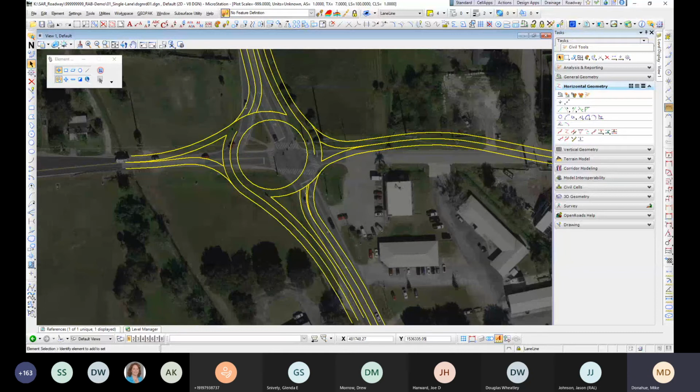I do see a question about DOT requirements with different vehicles, swept path analysis inside minimum radii. I default, and most of my colleagues and people who've tutored me up on roundabout design default, to the NCHRP document. FDOT locally has more guidelines regarding the types of vehicles they want to see, but it's really intersection specific. It pertains to the type of volumes and users you have at any given intersection. The reality is you may not have to provide all turning movements for a larger tractor trailer. For example, on this corridor, the east-west traffic has very infrequent, if any, large truck movements, but the north-south through movements have to accommodate the larger vehicles. So you have to take it all into account when you're vetting your swept path.